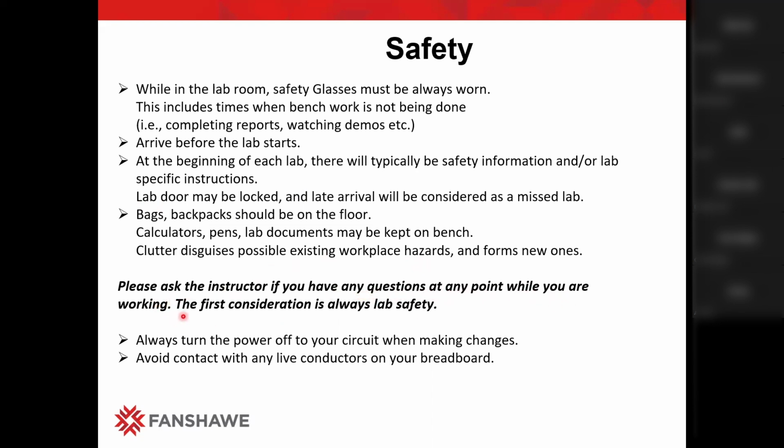Yeah, okay, that's pretty much a given. That's why you are here. That's why I'm here. The first consideration always is lab safety. It has to be said, it has to be understood, and it has to be followed. Always turn off the power to the circuit when making changes. Well, pretty much a given. Avoid contact with any live conductors on your breadboard. Had to be said.